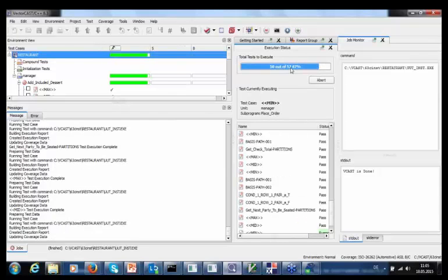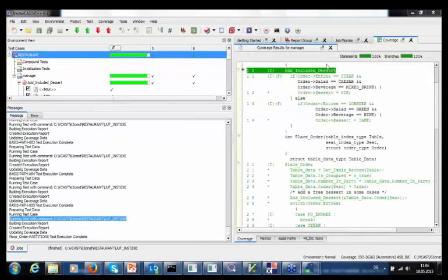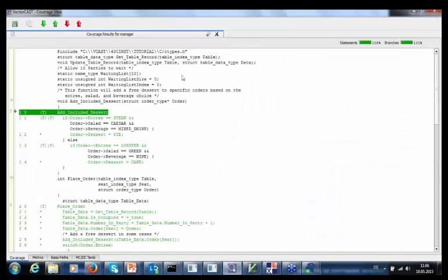So if I analyze the coverage that's been achieved, I can see that through this automatic analysis, I've generated a test harness that gives me 100% statement and branch coverage. I can open that up and I can check that this would indeed satisfy the certification requirements for code coverage at decision and statement level. Now, of course, that's not testing.